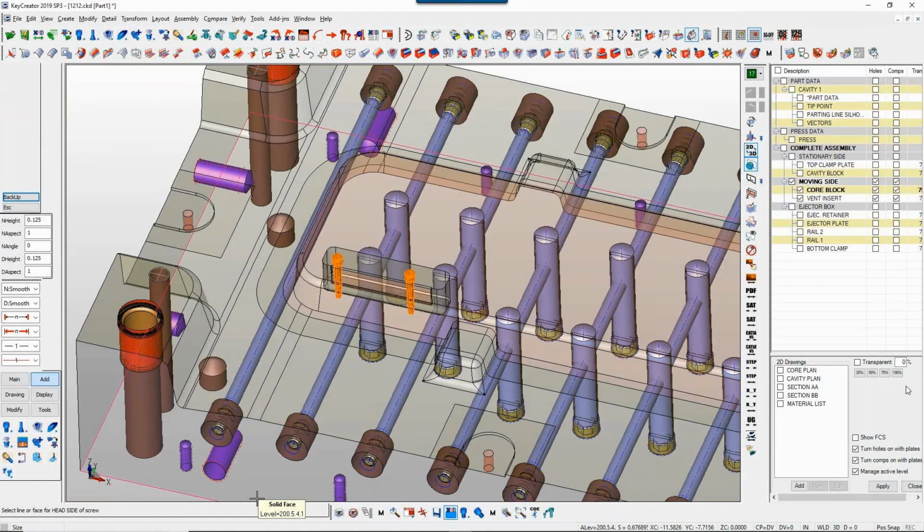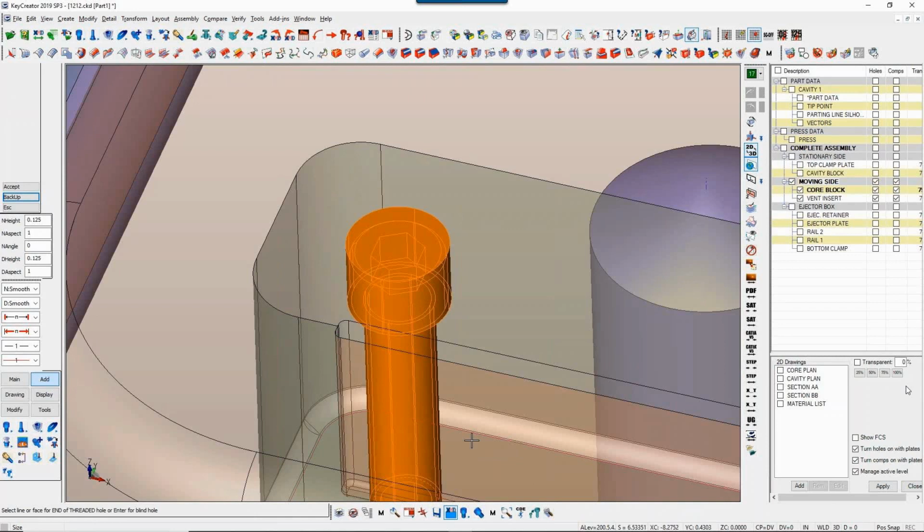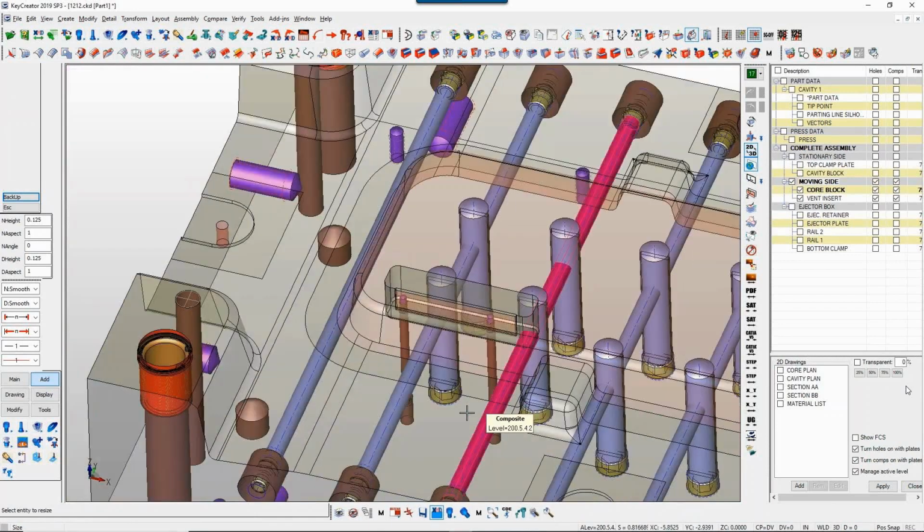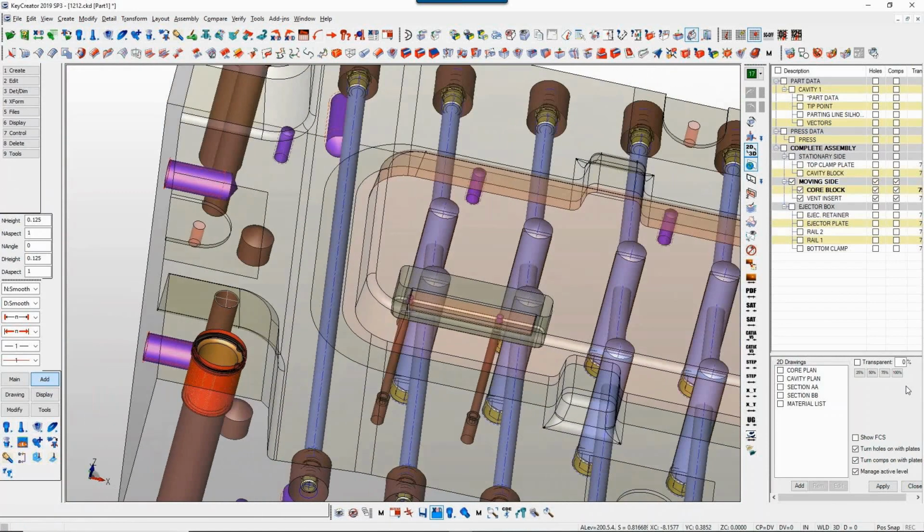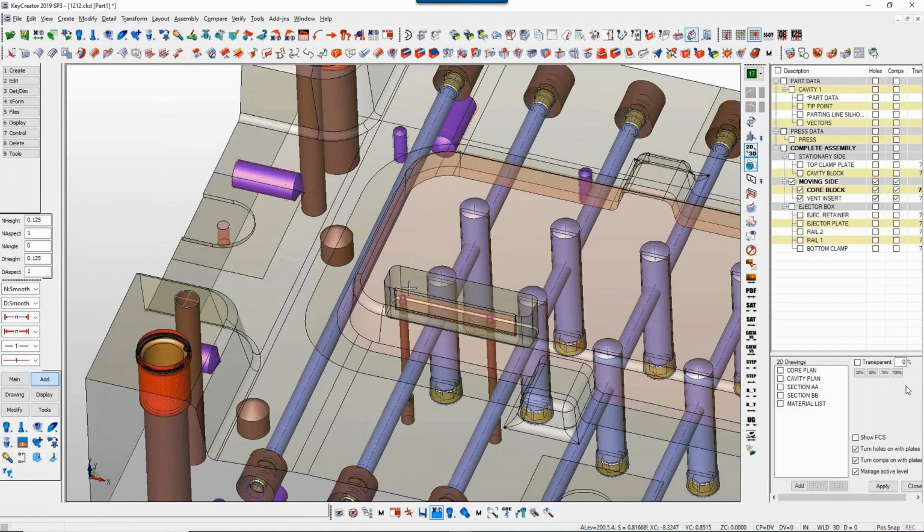I'm going to say redefine lines. So basically I'm telling it to start the screw at the back of the core block now and start the thread at the bottom of the insert, right? And it flips them around, resizes them accordingly, and the holes switch. Tapped holes now in the insert, and the clearance holes now in the core block.